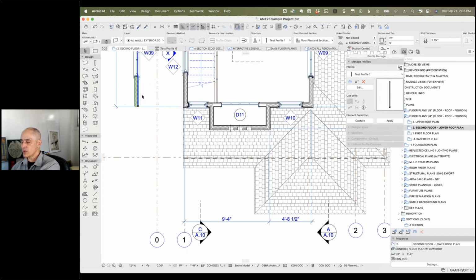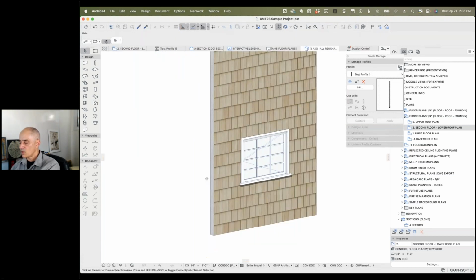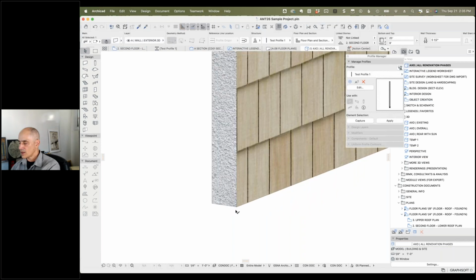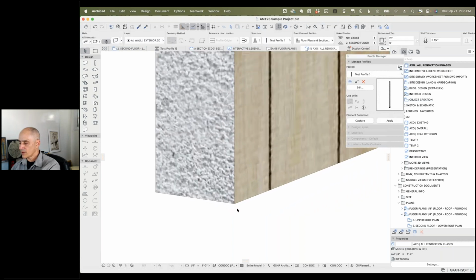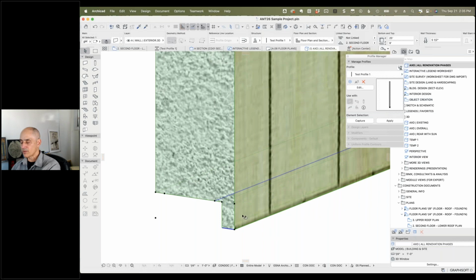And if I were to look in 3D with just that wall, we'll see that when I select it, there's now this little edge, and I can go and use that offset modifier and say, you know, I want to move it down. Okay. Now, right now it's showing the edge with an override.